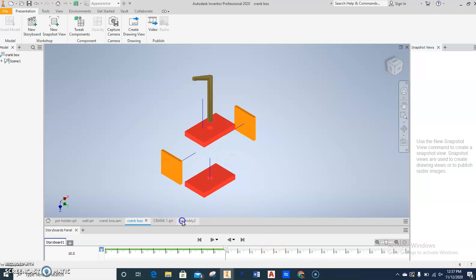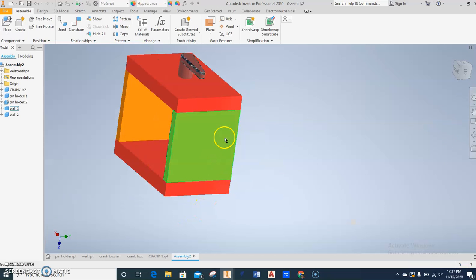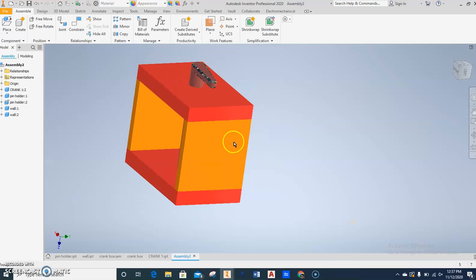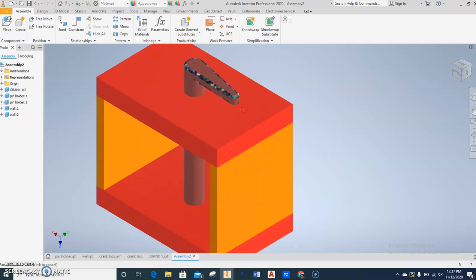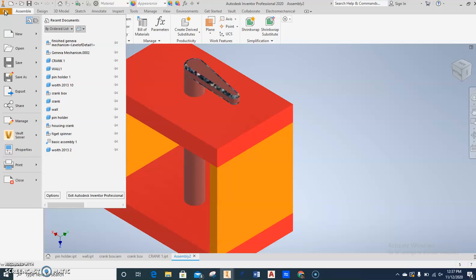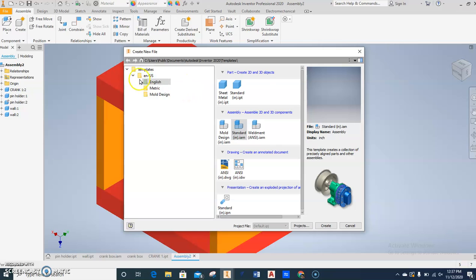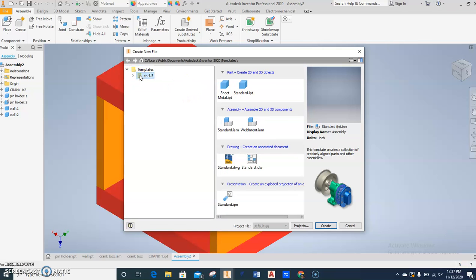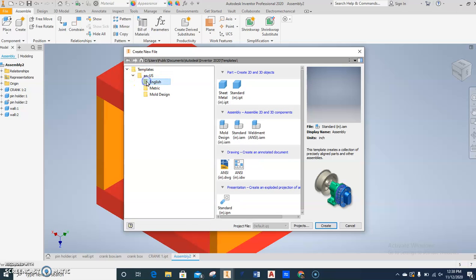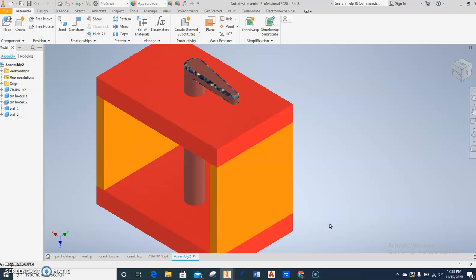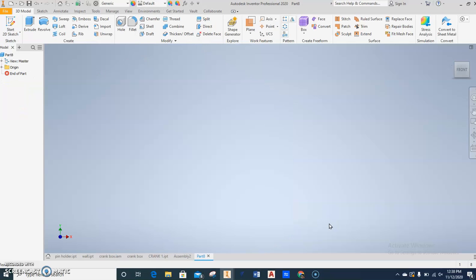All right, here we go. So you opened up Inventor and you hit start working. Okay, I don't have that screen just because I've done it enough. All right, so next thing, hit file, hit new, and this dialog box will pop up like this. So yours will probably look something more like this. You need to click this down arrow right here so you have more options. Choose English. And you're going to go to standard in.ipt. Click that, press create. It might take a moment to load. And once it's done, let's get going again.